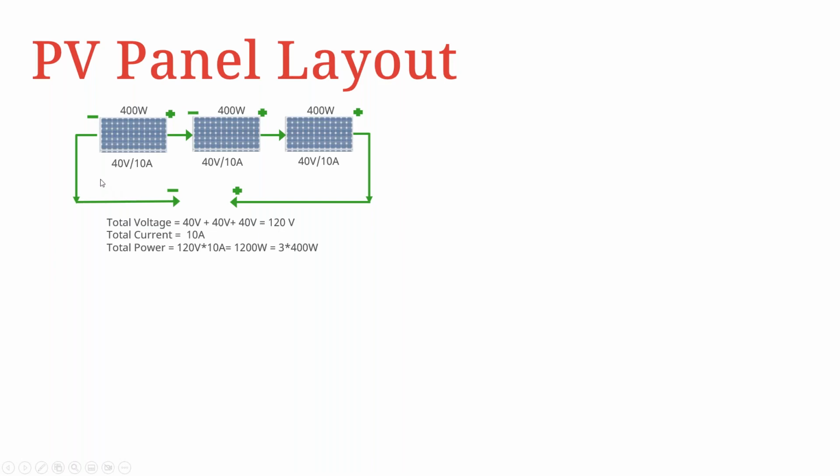In terms of the current, the same current that passes through one panel passes through the other panels, so long as they're connected in series. So you have a common current, which is 10 amps, which is also the specification on the respective panels, as you can see. The total power will be 120 volts, the summation of all the voltages of the respective panels, multiplied by the total current, which is 10 amps. This gives us 1,200 watts or 1.2 kilowatts, which is 3 times the capacity of one panel, that is 3 times 400. So in this case, this design is correct.